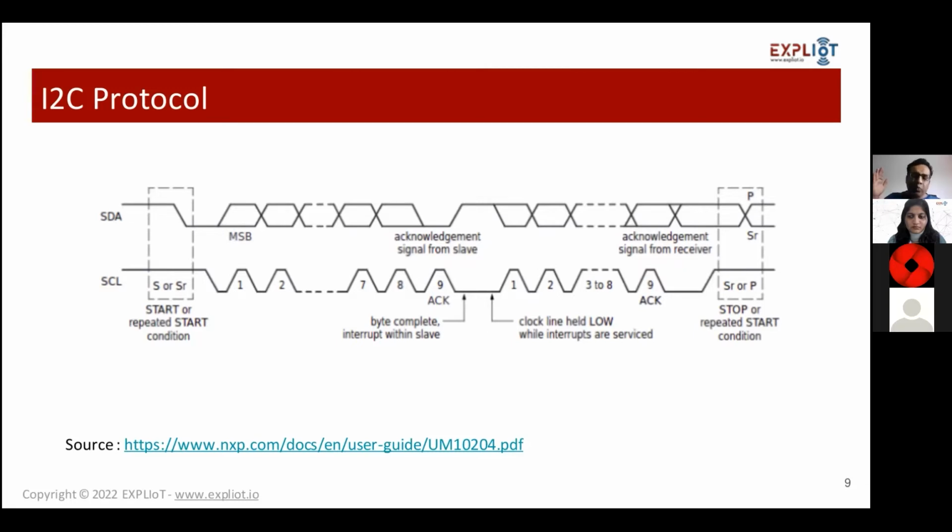Most of you who have worked with the I2C protocol, when you begin, and even if you're a professional at a particular point of time, will see this NACK happening over a period of time, right? It is a kind of pain for embedded systems designers to see that NACK signal. Once you are done with the data transfer, the data continues, 8 bits, acknowledgement, 8 bits, acknowledgement, likewise. And then at the end, you have the stop condition where it wants to end the communication between the master and the slave.